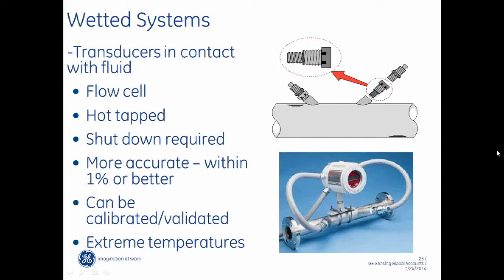Can clamp-on be used in steam flow measurement? It can, and we've done it. We don't do a lot of it, mainly because we have to make sure the steam is clean, but the biggest part is getting that clamp-on sensor onto the pipe.